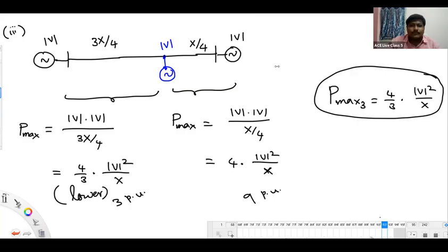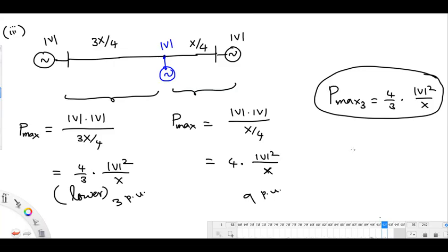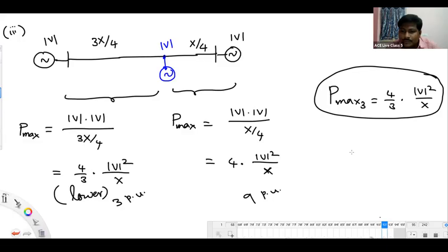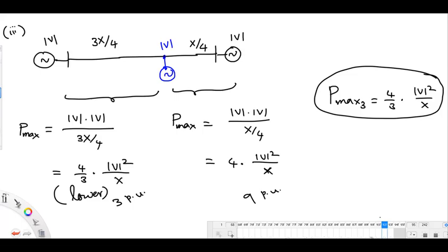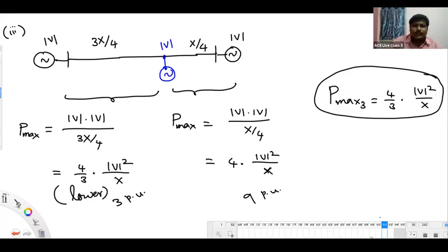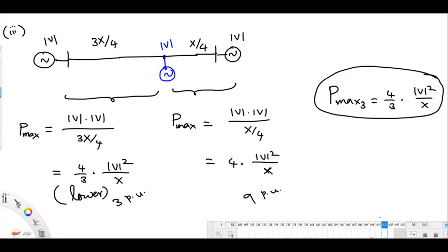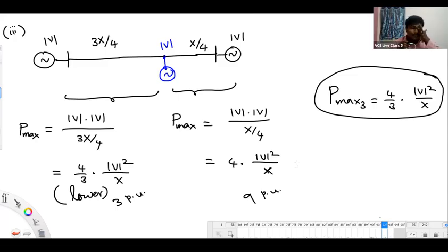Sir, can we say the synchronizing power is the coupling strength of the rotor? To maintain coupling strength, we have to consider the synchronizing power. Sir, I'm asking whether I can take it that way, for methods to improve steady state stability. See, if the synchronizing power coefficient is very, very high, that is an indication of accepting disturbances, right?